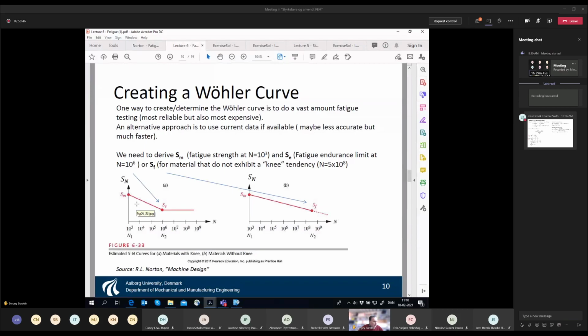If we come to this point, it means that we have already used up some of its capability to withstand the loading. And if we come to the red line, this division line, then we took it all. We completely exhausted the possibilities to resist the loading. So the damage here is 1, and the damage in the beginning is 0.